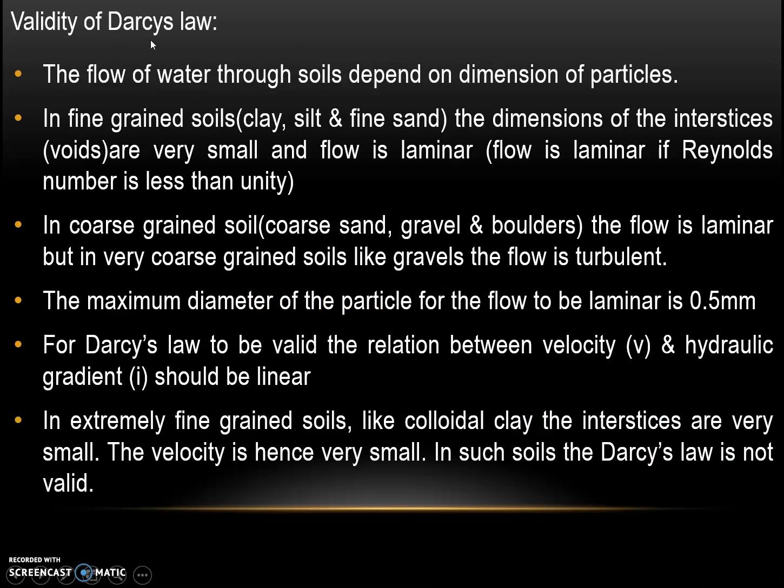Next we'll go through validity of Darcy's law. The flow of water through soils depends on dimension of particles. In fine-grained soils, that is clay, silt and fine sand, the dimensions of the interstices, that is voids, are very small and flow is laminar. Flow is laminar if Reynolds number is less than unity.